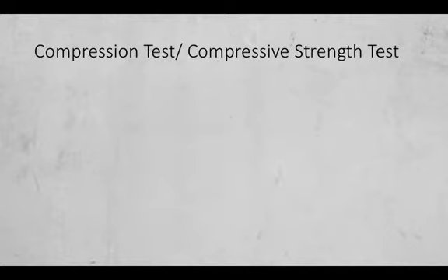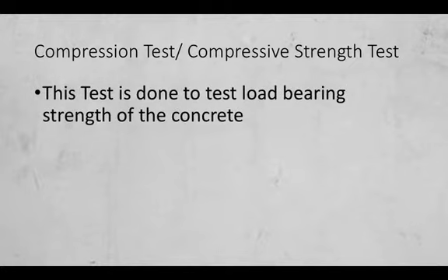And there you had a video just showing you the procedure involving the slump test. So now we're moving on to the compressive strength test or the compression test. This test is done to test the load bearing strength of the concrete.